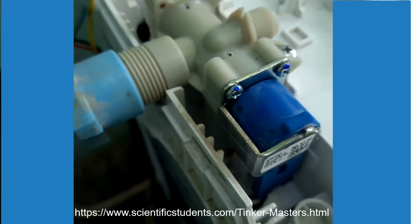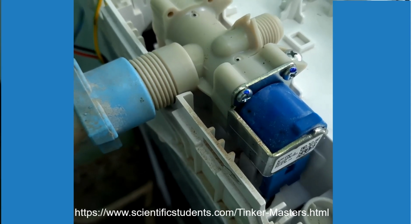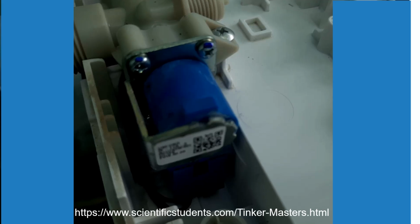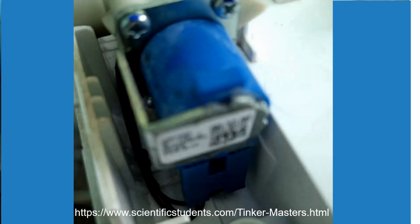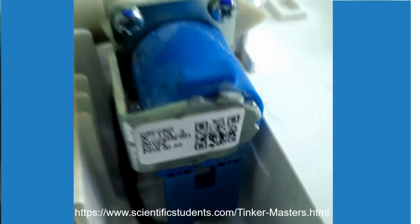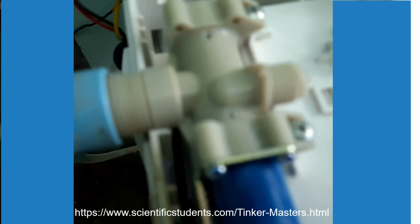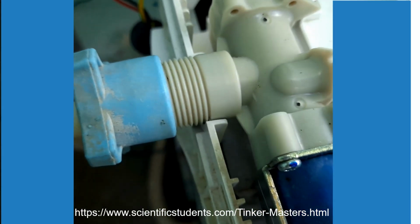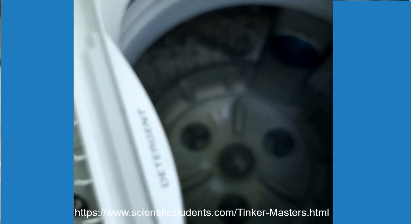My dear students, this is a water intake valve, a kind of solenoid. Whenever the motherboard gives power to this particular coil, it becomes an electromagnet and pulls the lever inside this valve, and whatever input water you have opened goes into the water drum here. Okay, you understand?